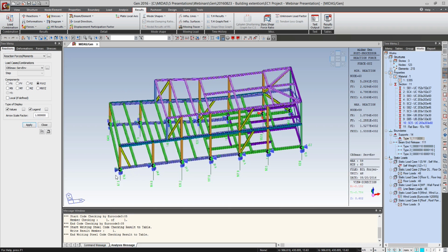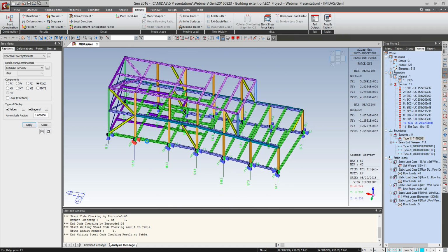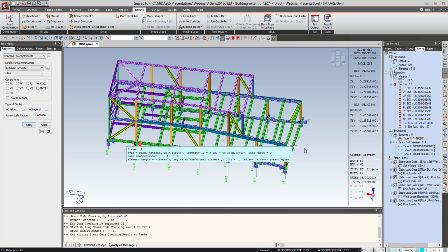As expected, the values in the exterior were smaller than the ones in the interior, and three types of systems have been used for transmitting the loads to the existing structure. One for those where the load coming from the newly constructed structure was about 152 kilonewtons, then one in the range of 100, and one for the ends.